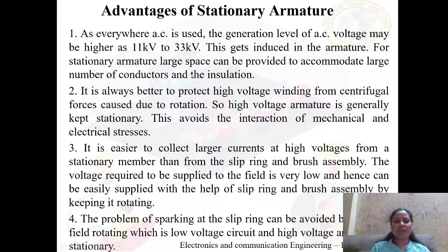For a stationary armature, large space can be provided to accommodate a larger number of conductors and the insulation. The second advantage is that it is always better to protect the high voltage winding from the centrifugal forces caused by rotation, and hence the high voltage armature is generally kept stationary.